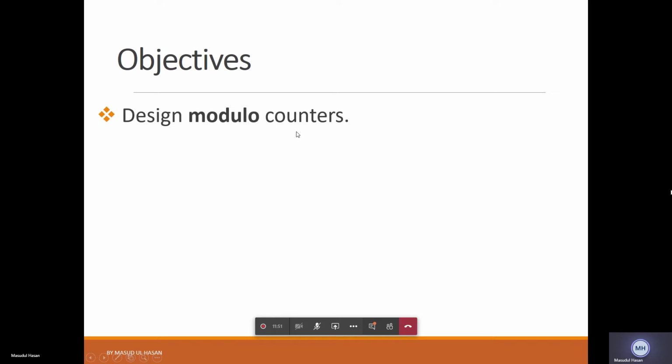But we can play with the clock. If we provide this clock to the first counter and don't provide the clock to the next 2 counters, what will happen? The first counter will work, and when we want the second counter to be enabled, instead of CE we can connect the clock at this input, or keep it at clock and provide the clock at that time only.